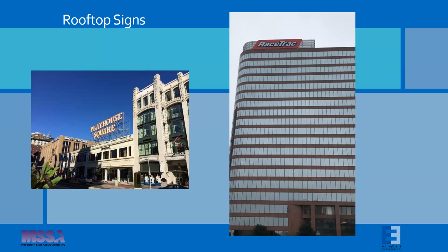One of the things I also like to point out about the one on the right is that because it's located in the corner, we wrapped around the corner of the building with that screening wall. All that stuff had to be designed. The sign itself is over 100 feet wide. So there were a lot of interesting design elements and challenges when you have it roof mounted. You've got extra wind pressure from that. You have it at the corner, extra wind pressure, and then you have this frame that's going around a 90-degree corner. The way you design it to fit onto an existing roof of a building that had already been built was a lot of fun.